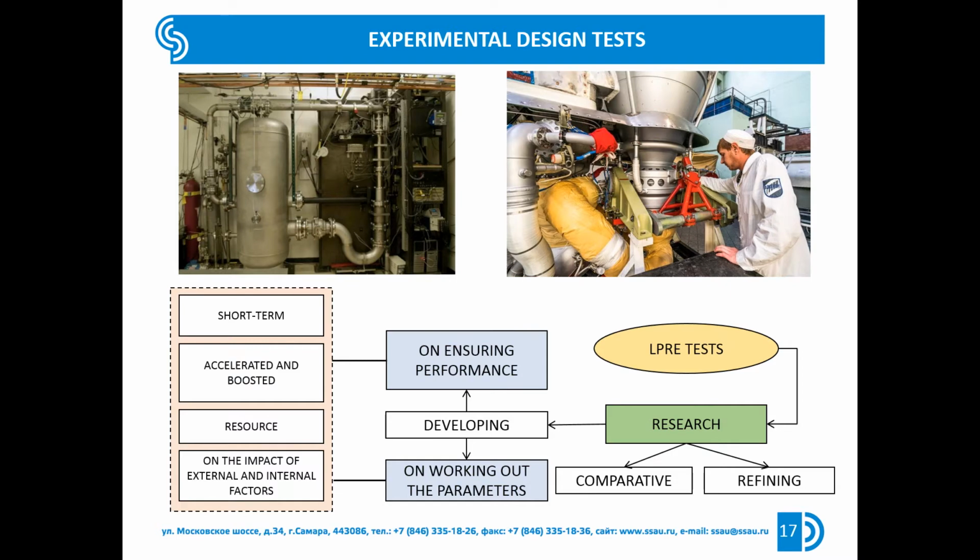The purpose of refinement tests is to refine the design of liquid propellant rocket engine components and the engine as a whole to meet its performance specifications, which is achieved by identifying and eliminating factors that degrade performance and reduce the performance parameter reserves of the liquid propellant rocket engine. The following tasks are solved during developmental testing. Refinement of the LPRE component design and the verification of the correct choice of materials and technology for manufacturing parts to ensure durability and reliability.